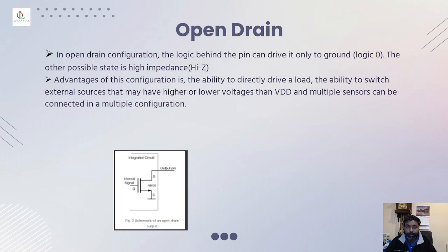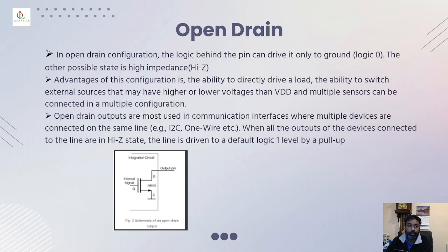The one difference in open drain is it doesn't have a PMOS, it has only NMOS, and if it wants to be connected as close to VDD, then you need an internal or external pull-up resistor to make it operative. So if you take 8051, all the GPIO pins are configured with open drain because it's just how they're manufactured, and that's how they program on that.